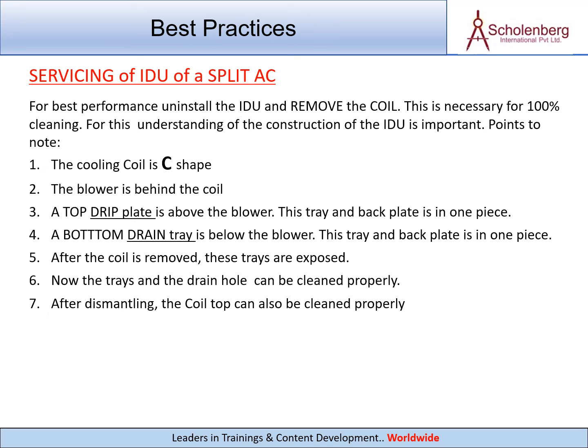Servicing of IDU of a split AC. For best performance, uninstall the IDU and remove the coil. This is necessary for 100% cleaning. For this, understanding of the construction of the IDU is important. Points to note. 1. The cooling coil is C-shape. 2. The blower is behind the coil.